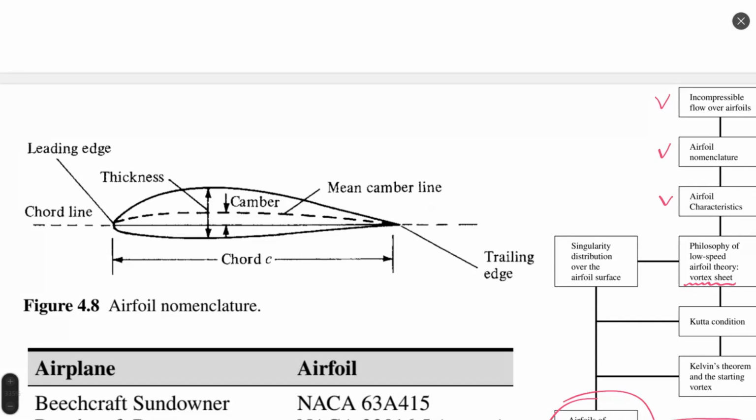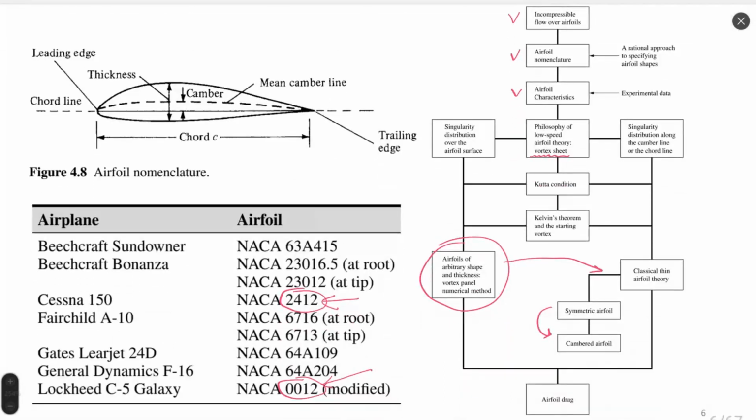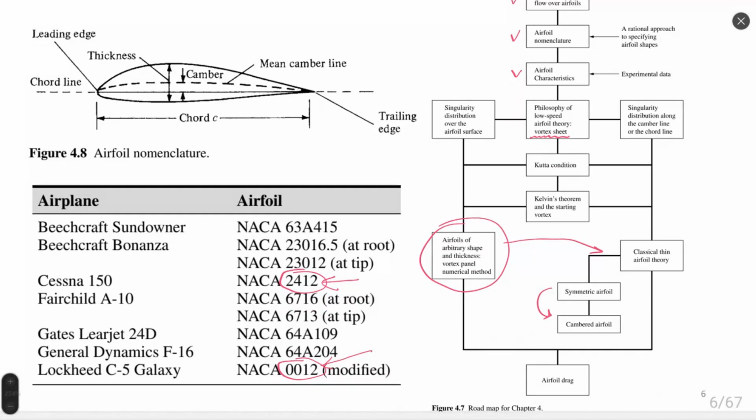Very interesting question. I never thought that it could be positive. Camber line curvature could be positive for a thin airfoil. There are different airfoils for different applications. There are airfoils which have an extremely curved camber line, for example airfoils used in turbomachinery, because the main objective is to transform energy and also to rotate the flow direction by some certain angle.